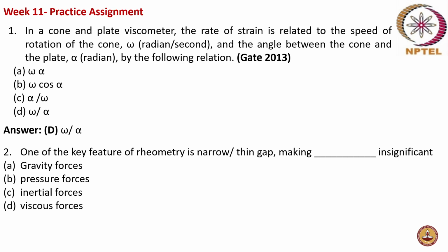So why is this narrow gap actually used? Is it to make gravity forces insignificant or pressure forces insignificant or inertial forces insignificant or viscous forces insignificant? Which of these becomes insignificant when you have narrow or thin gap? It is actually the inertial forces. To make the inertial forces insignificant, you have a narrow or thin gap. So when you have the force balance equations, in order to cancel out the inertial forces, you have the thin gap or narrow gap. Okay.